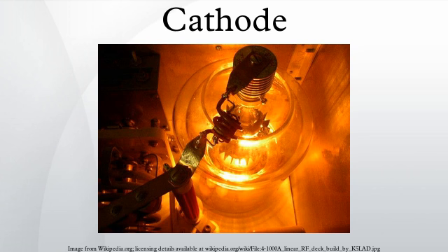There are two main types of treated cathodes. Coated cathode: in these the cathode is covered with a coating of alkali metal oxides, often barium and strontium oxide. These are used in low-power tubes. Thoriated tungsten: in high-power tubes, ion bombardment can destroy the coating on a coated cathode. In these tubes a directly heated cathode consisting of a filament made of tungsten incorporating a small amount of thorium is used. The layer of thorium on the surface, which reduces the work function of the cathode, is continually replenished as it is lost by diffusion of thorium from the interior of the metal.